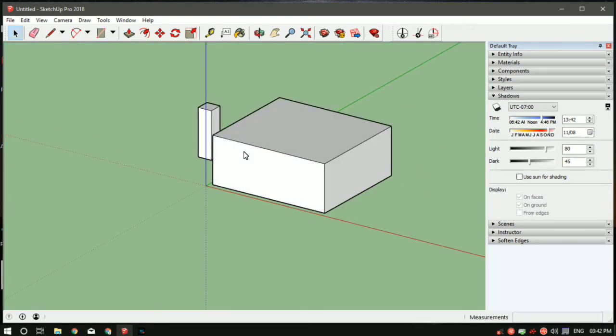So if you're having many rectangles, and many objects which you want to extrude, and know that the height of each and every object is same, you can just extrude one object and then use this technique to make the other ones quickly.